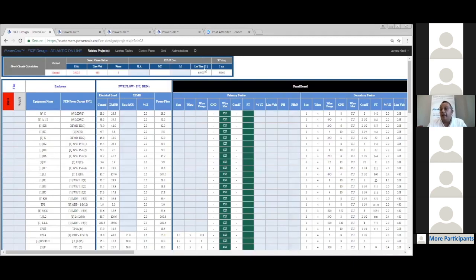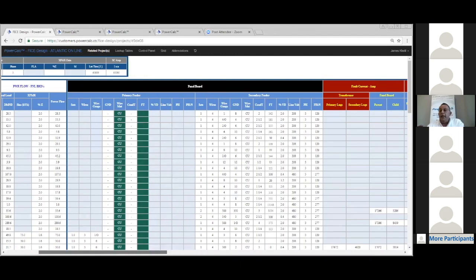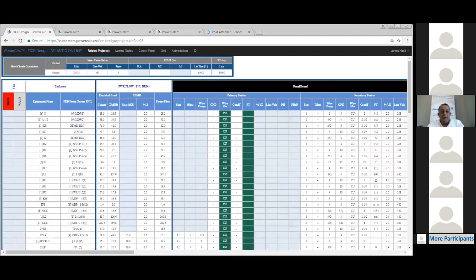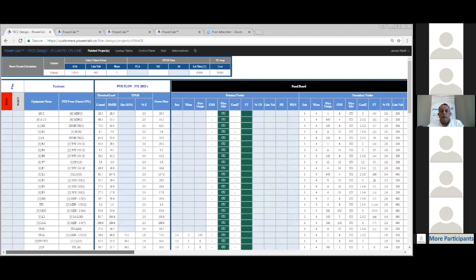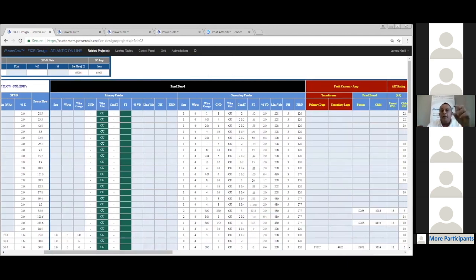So now it changed the value from the 51 to the 65, and that would be your base point for the calculations downstream all the way to the last panel on the power distribution system. Still, we don't have any information in here because we need to input one of the most important items in terms of calculating the fault current. It is distance sensitive. So we still have to go from one panel to another and put the estimated length